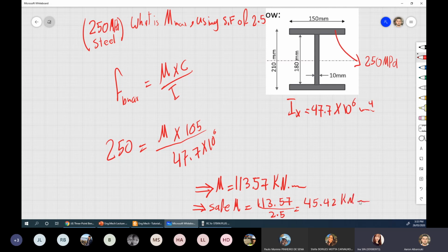So it's the same thing. You can, if you want, leave the safety factor. In fact, maybe it's an easier way for you guys now. Leave the safety factor till the end. Do your calculations properly and apply the safety factor at the end, and make your judgment there by multiplying or dividing. All good?